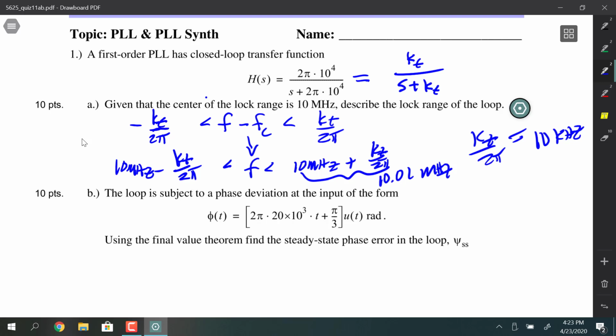That's the nature of phase locked loops, though. The carrier frequency can be high and the tuning range is going to be small because it's just an allocated bandwidth. If you were demodulating a signal with this phase locked loop, you'd be able to demodulate an FM signal that would have a message bandwidth of around 10 kilohertz or less, maybe only 5 or 8 kilohertz. And then the loop would be a little bit wider than what it needs to be.